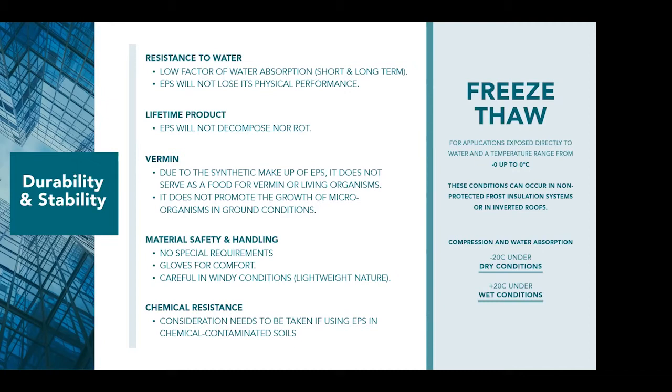So, resistance to water, I've already mentioned that on the last slide. We have a low factor of water absorption, short and long term, when we look at an EPS, so it doesn't lose that physical performance. If you use an EPS, you'll have confidence in that project that the compressive strength stated in your DOP from the core is going to be maintained over the lifetime of that project. Other materials may not stack up quite the same. So EPS is definitely a lifetime use.